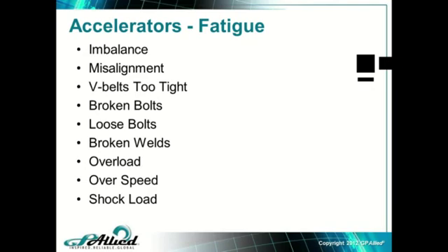It's about 5 times L10. So the business case then for helping an organization understand to not allow these things, or upon finding them, get them fixed quickly, is that every one of these is taking that mean time between failure for the bearing, and the longer these are, the more severe they are, and the longer we allow them to stay in the machine, our mean time between failure is just continually dropping.